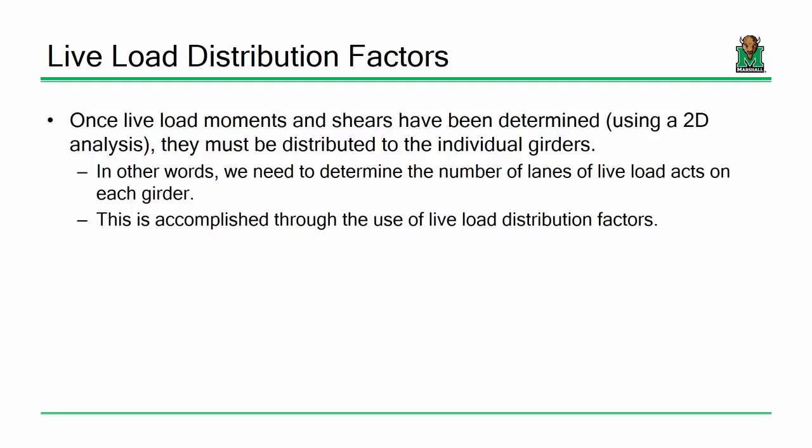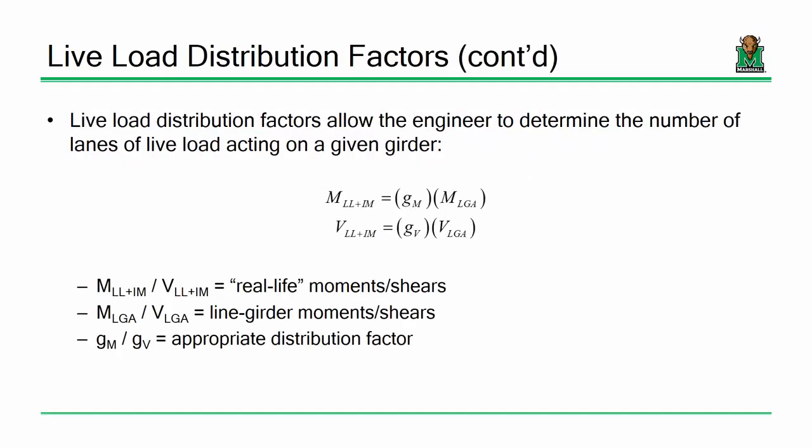I have to then translate that into what I would call real life moments and shears. In other words, how much of that analytical model that you just utilized, how much of those moments and shears are really going to the girders? And that's where live load distribution factors come into play.